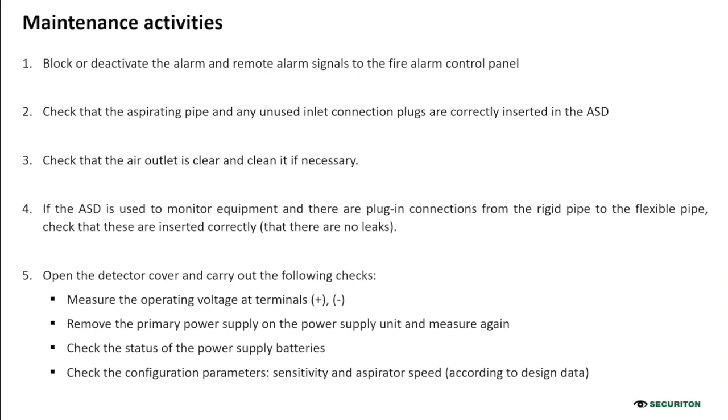So I numbered all the activities that have to be done on the ASD device. First of all, you need to block or deactivate the alarm and the remote alarm signal to the fire alarm control panel.